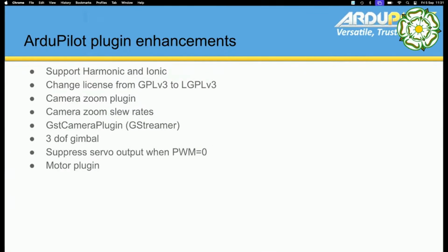And then we've added some features around camera zoom plugins, ability to stream. We've added gimbals. There's work going on to make sure that we correctly suppress servo outputs before the vehicle's initialized, so it doesn't jump around while it's starting up. And there's some work to add extra plugins as part of our GSoC projects as well.